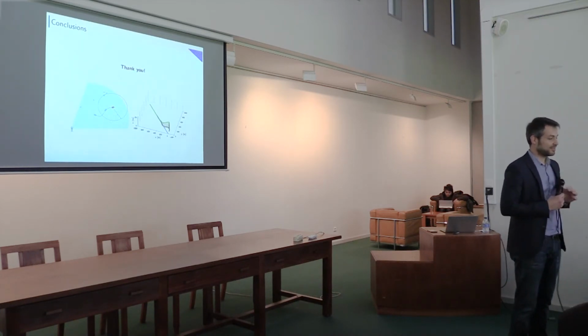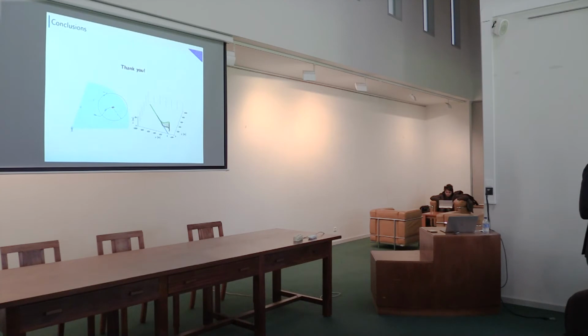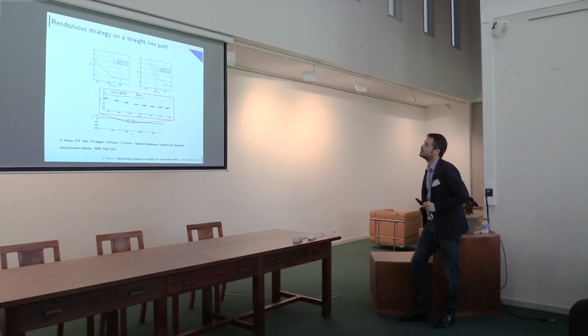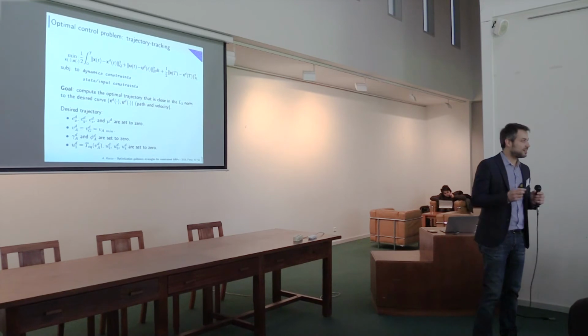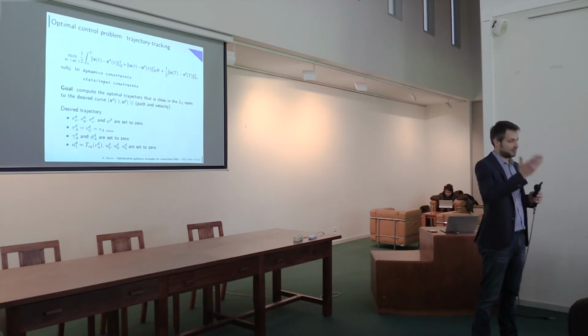Well, that was about the optimal control problem. So how do you select the terminal constraint? For the straight line, you have some properties of the optimal control problem, and you have to set that up. So there is a matrix over there, which is P1. For the straight line maneuver, you know that at the end of your trajectory you are in a trim condition. You are going straight with a fixed velocity, fixed airspeed, and so on.